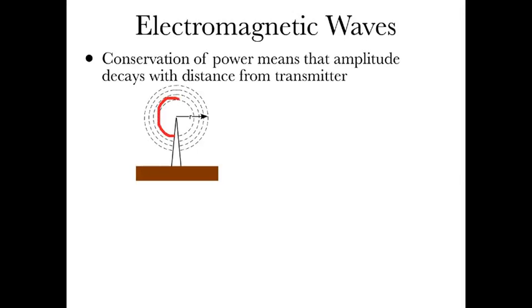If you look at a specific distance r from the antenna, the power, if you integrated the power over that sphere, right, we're in 3 dimensions here, that has to be the total power radiated by the antenna. If you go out a bit further, that power cannot be unchanged. We're essentially assuming that the wireless medium is lossless, so there can't be a power change.